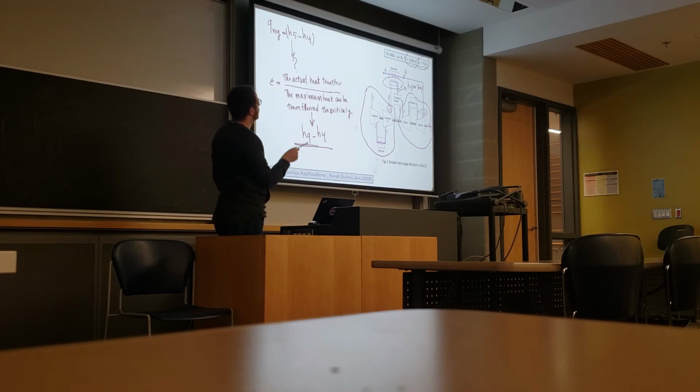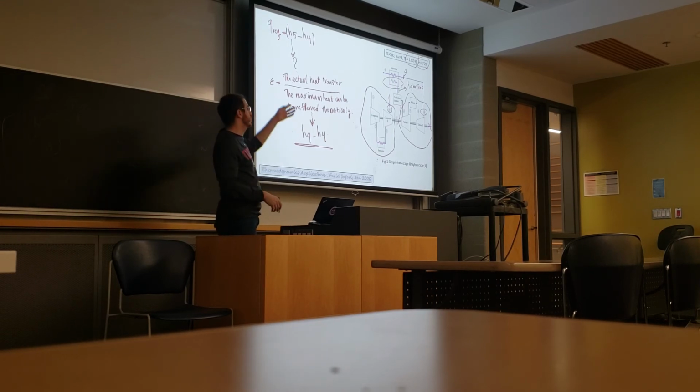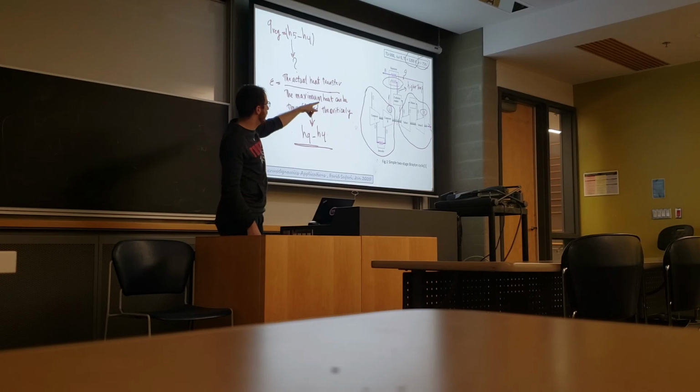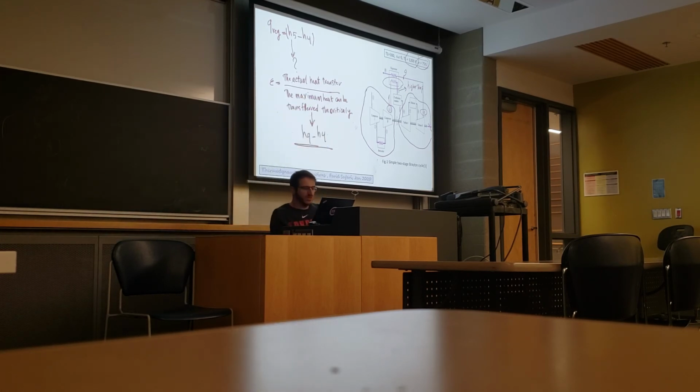The maximum is the difference between the hottest flow and the coldest flow in a heat exchange process, in which we have 4 flows here: 9, 10, 5, and 4. So this is the denominator, and the actual heat transfer is H5 minus H4. So H5 minus H4 is what we are looking for, right? So epsilon times H9 minus H4 equals H5 minus H4.